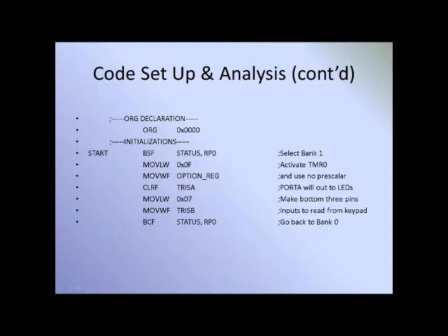The other bits are just used for RB5 through RB3 for the keypad rows, and to drive the motor, RB7 and RB6. The option register was loaded with 0F hex in order to activate the timer mode of timer 0.